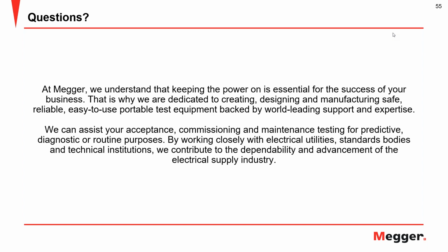Yeah, so thank you, Dennis, for pointing that out. That's a very important point and kind of why I wanted to comment on that. So the PDIV and PDEV are two very important measurements when performing partial discharge testing. And those are the partial discharge inception voltage, which is the voltage at which partial discharge starts to take place, and then the extinction voltage, or PDEV, which is the partial discharge extinction voltage, which is the voltage at which the partial discharge ceases to happen. And these are not always at the same voltage as Robert had mentioned and Dennis pointed out.